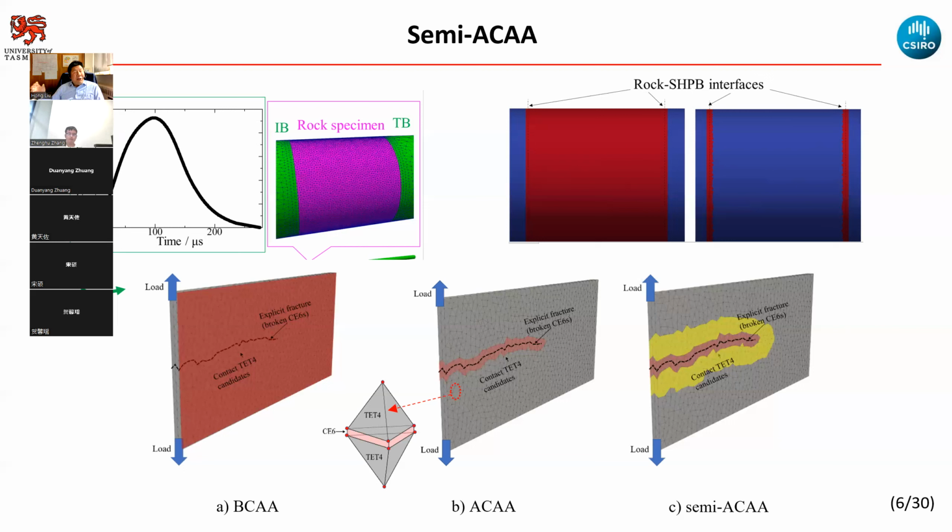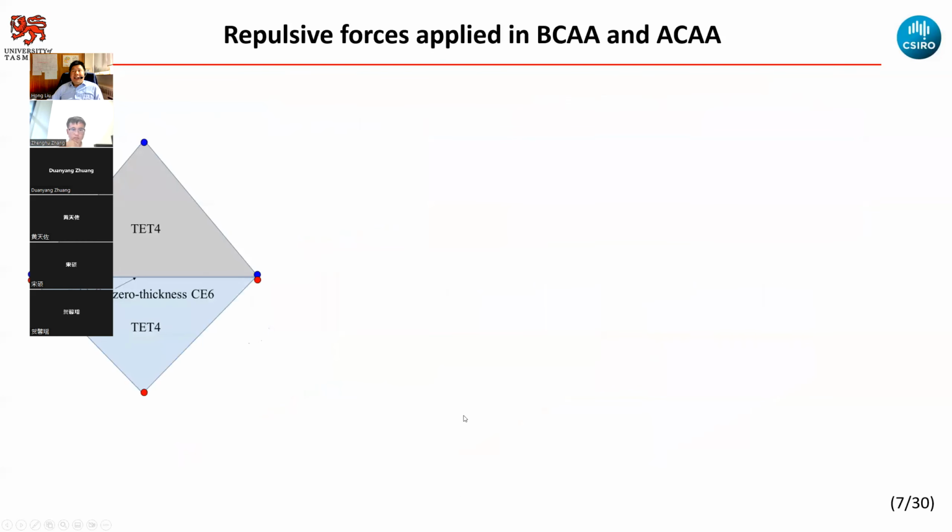If you do not deal with that macro damage, it will cause spurious failure. So around the macroscopic failure, we consider a zone, and for this zone we simultaneously apply the boundary stress and the contact force. In that case, we can gradually reduce the computation capacity required. That's why we are able to model a bigger model.